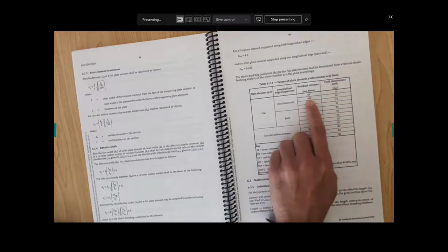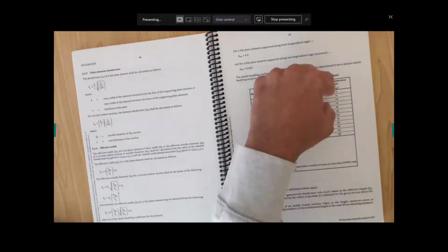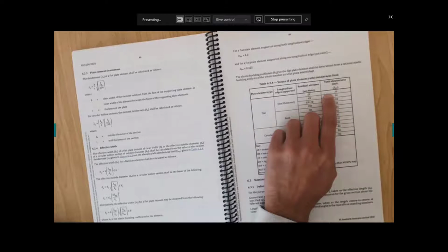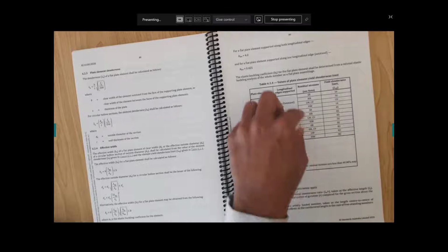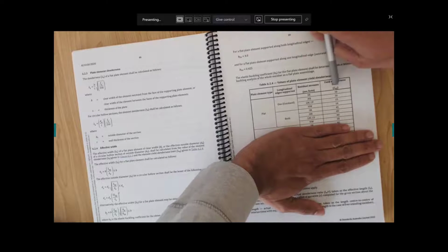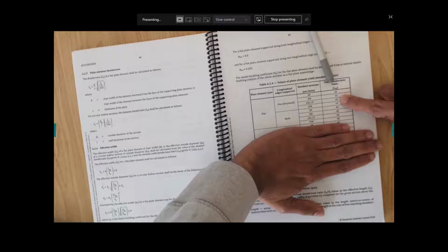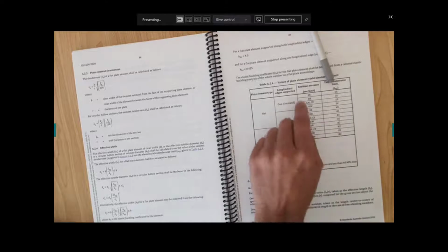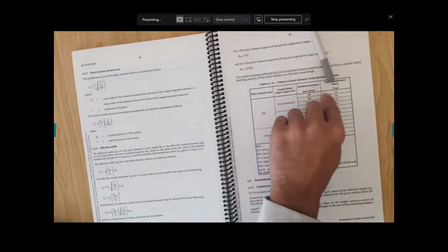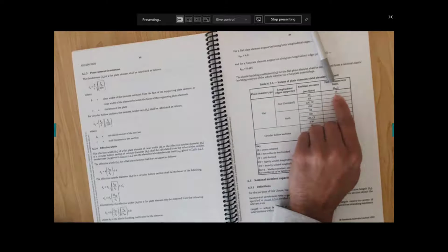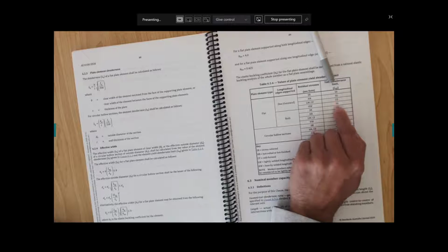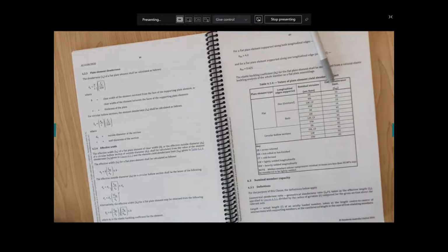Particularly the first line, meaning that look at these numbers, I need to physically explain what these numbers are: 16, 16, 15, 14, and look at these numbers here. Don't worry about the circular one, but you can see the significant difference: 16, 15, 15, 14, and 14, 45, 40. This number is telling me that the smaller the number, the more prone to buckling. This element will buckle first. That's what these numbers physically mean.